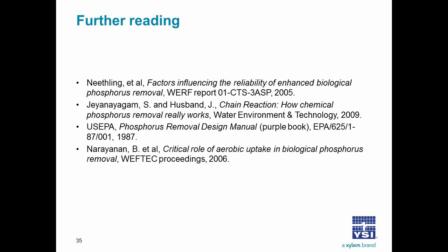Increased sludge production, and not only the total amount of sludge, but also the amount of inert solids. So if you're doing simultaneous precipitation, you're carrying additional inert solids in your mixed liquor. So that instead of having to carry a 4,000, say, for a mixed liquor that's 75% volatile suspended solids, you might have to carry 4,500 or 5,000 just to get the same amount of volatile suspended solids.